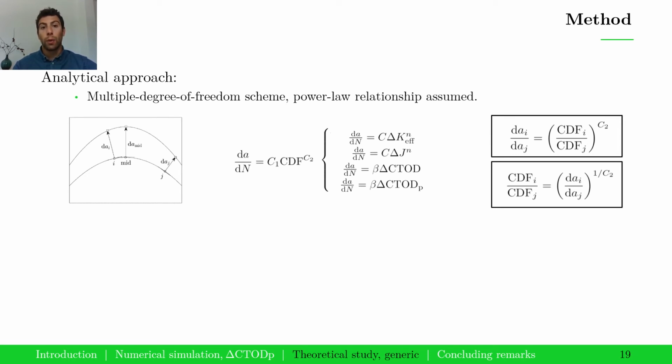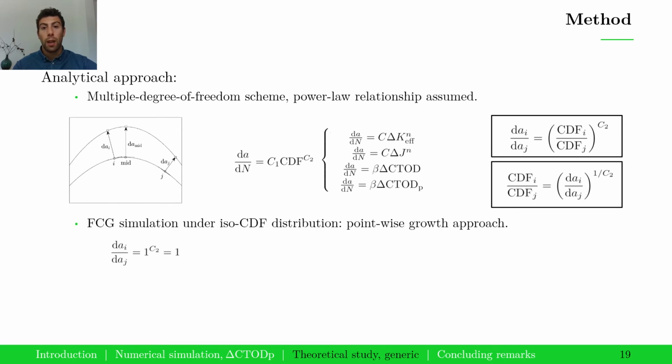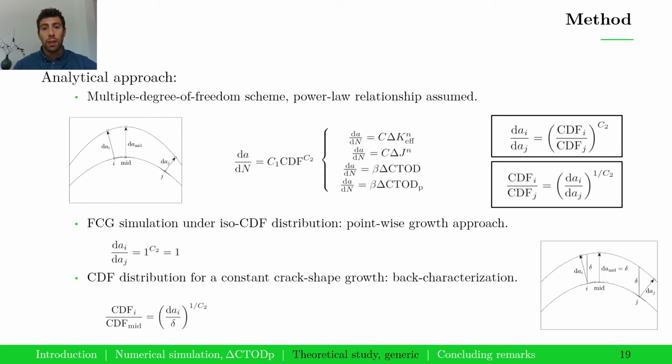So we do 2 theoretical exercises. In the first, we simulate fatigue crack growth under an iso crack driving force distribution by postulating different initial crack shapes, and in the second, we back calculate the crack driving force distribution required to achieve a constant crack shape growth.